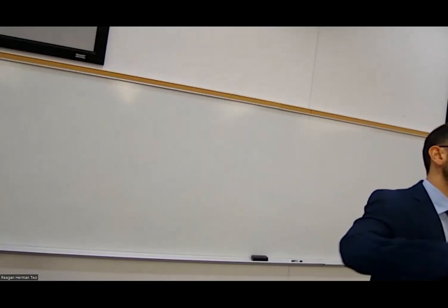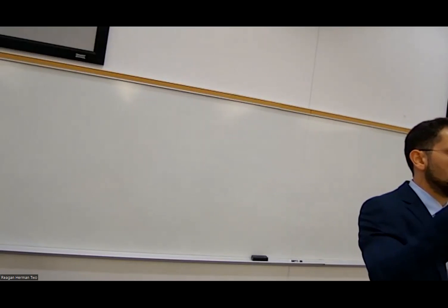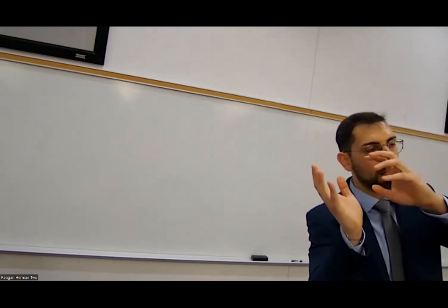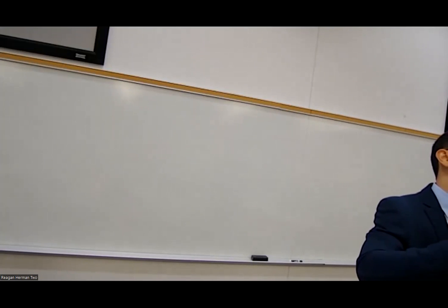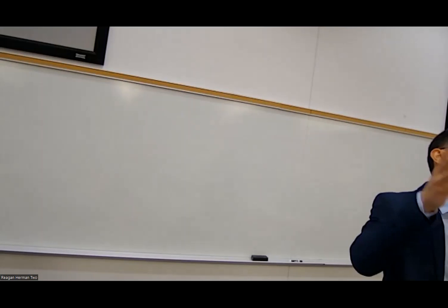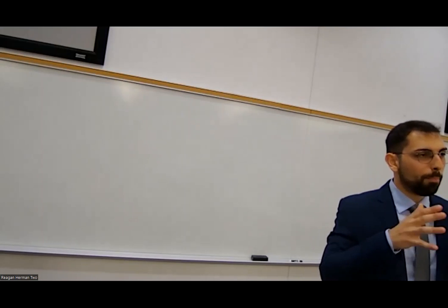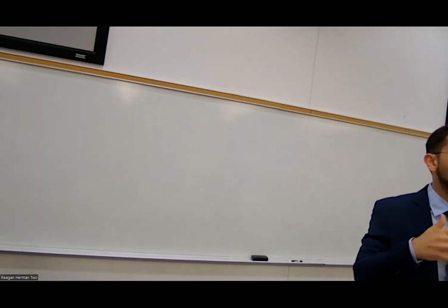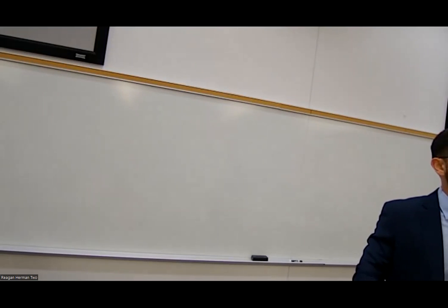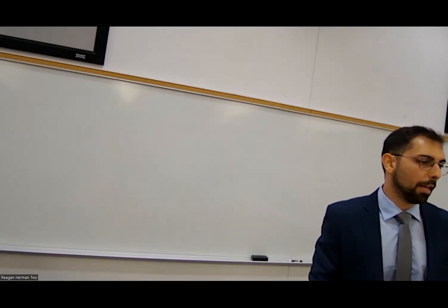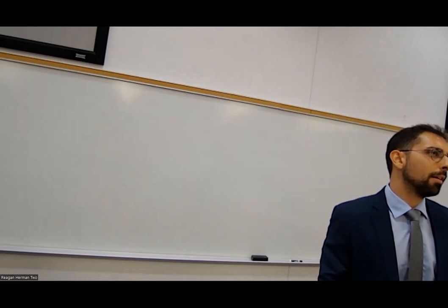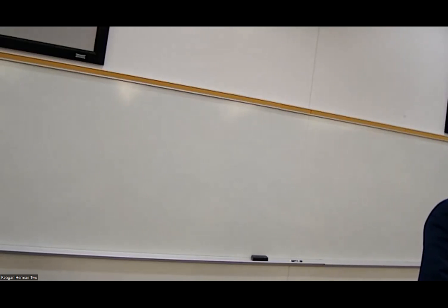So I mean, we're still looking into it, but so far it's a hypothesis because you can't be sure of them until you have done like 1,000 analyses. So what happens is when you have more shallow foundations, you have the wave coming through, the house is being pushed, then comes back more. Because they have, let's say, 5 PY springs, the plastic deformation that these 5 PY springs can experience is limited compared to when we have 15 springs. So it's more like there's not as much controlled energy dissipation in this case.